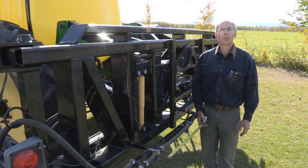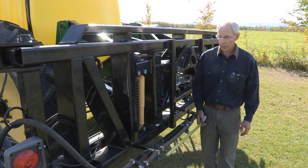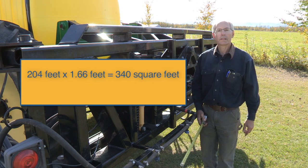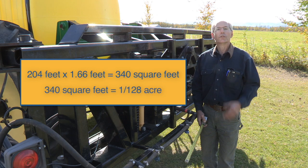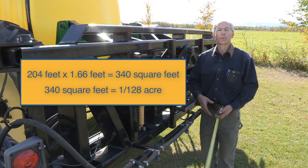Again, we're going to be using the 1/128th method of calibration. And what's significant about 128? Well, you know that's how many ounces are in a gallon, and the industry standard for nozzle spacing is 20 inches or 1.66 feet, and we're going to lay out a test course that is 204 feet long. So 204 feet by 1.66 feet is approximately 340 square feet, which is 1/128th of an acre. So you can make this direct comparison with ounces to gallons per acre.